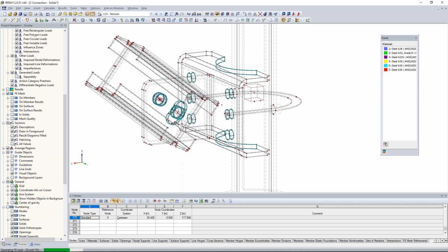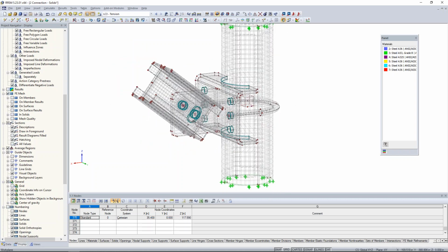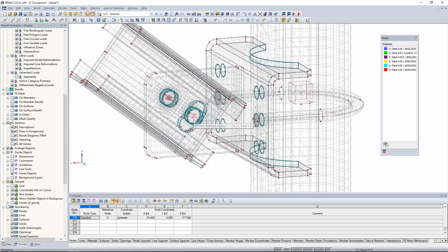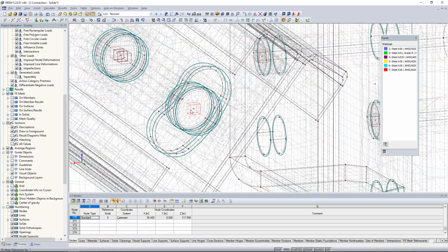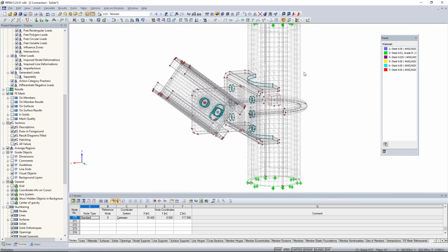Now, it will take just a split second longer because remember, we have really defined some of these smaller FE mesh elements for our bolts, but everything will still tie back into this 1-inch setting. So here we are with the final FE mesh. We can scroll into these bolts and see there's definitely a smaller length defined. Our pipe has slightly larger length defined.